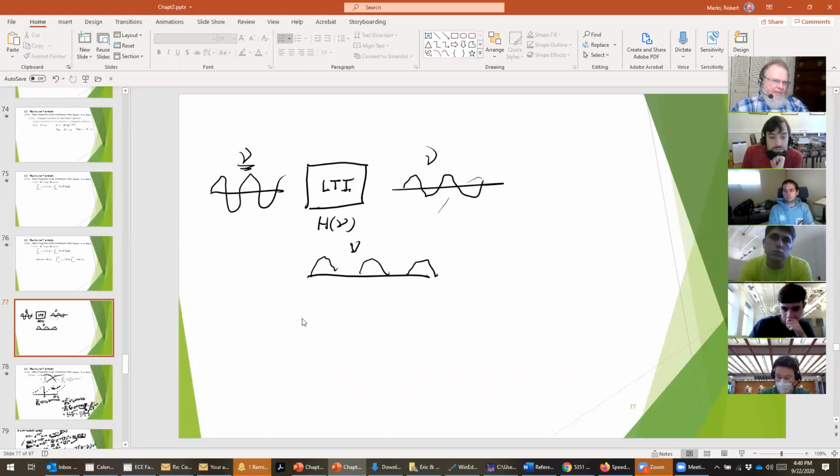So we're very limited in application of LTI sorts of systems. And anytime you have a nonlinearity, you have to go away from LTI systems. There's a generalization of system analysis called Volterra series, and that is applicable sometimes.